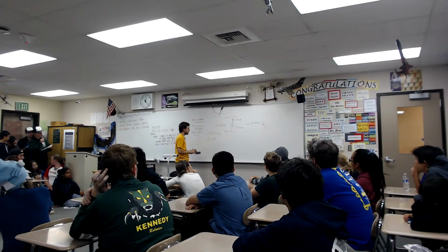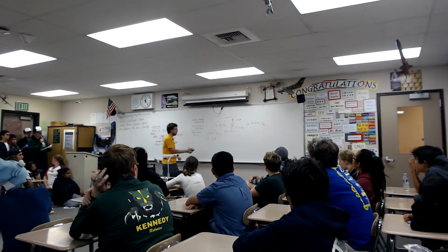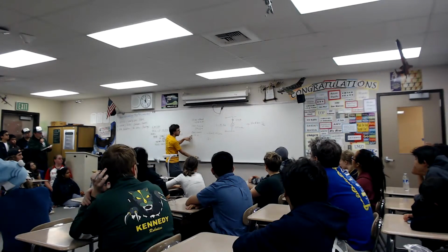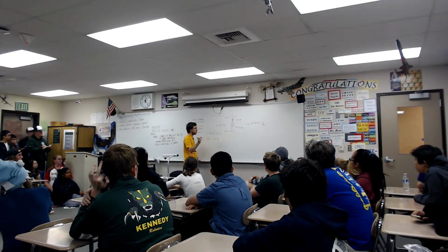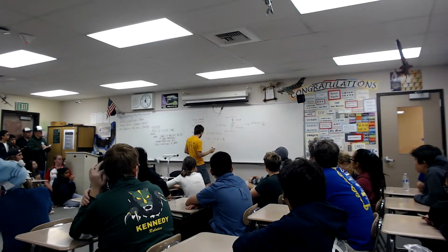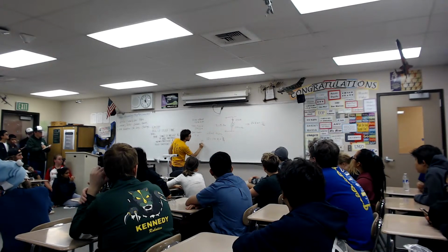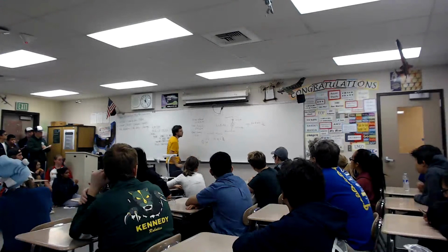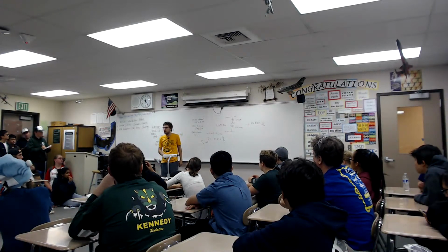Actually, sorry, what's I then at stall? So I is our stall current, 131 amps, times our resistance, and then you said omega is 0, so this cancels out. So there we go, we have 12. So we got our first unknown. From the data sheet, we can compute the resistance, which is pretty cool.